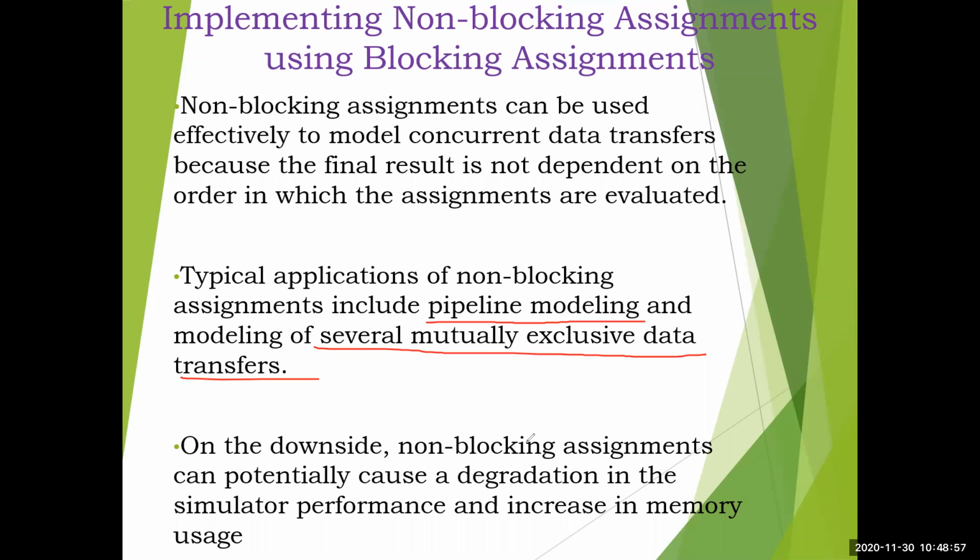On the downside, non-blocking assignments can potentially cause a degradation in simulator performance. This is the drawback of non-blocking assignments, and they can also increase memory usage, because internally they store the values without an explicit temporary variable. Because of that, memory use increases and performance degrades, which means delay will happen. So this is about blocking and non-blocking assignments, called procedural assignments.